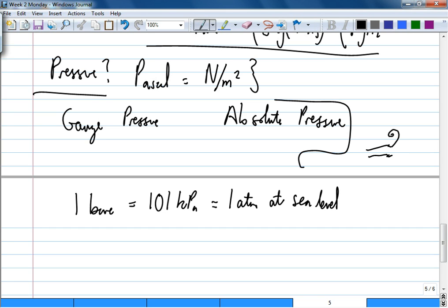When you go to a party, there's this thing that's coiled up like a piece of paper like this. And then when you blow, it straightens out. Seen before or not? So inside this mechanical pressure gauge is basically something like this. Inside here there's a coil like a snail. A coiled piece of, depending on what material it's made of, sometimes brass, sometimes stainless steel and so on.